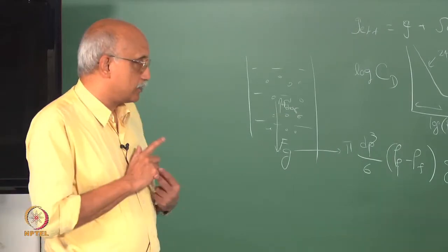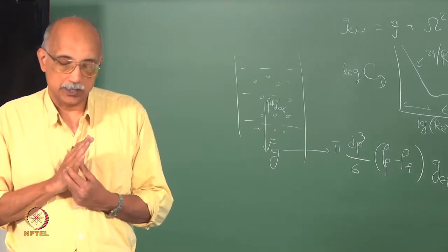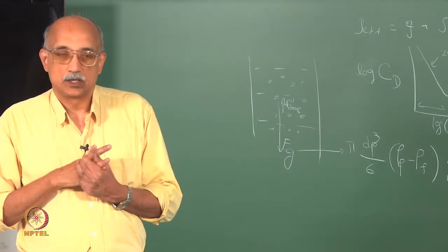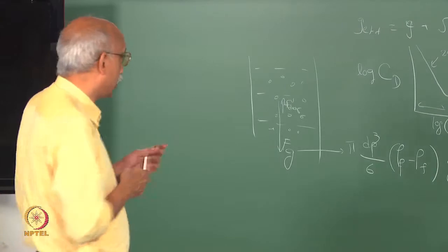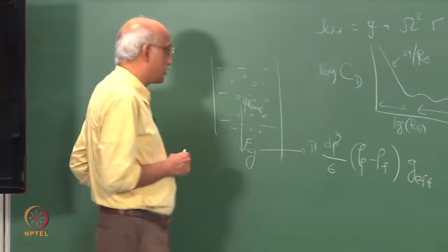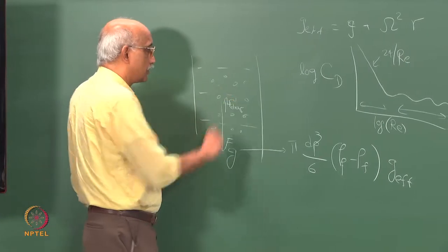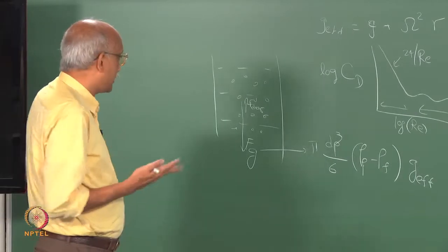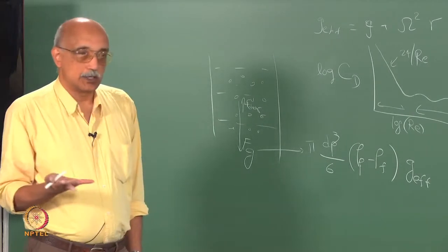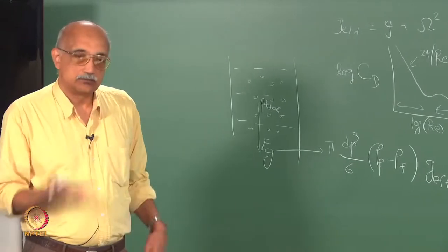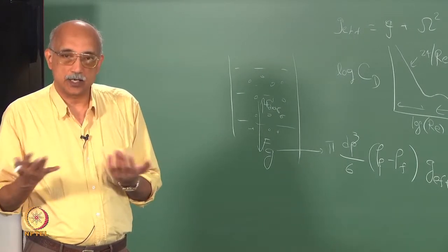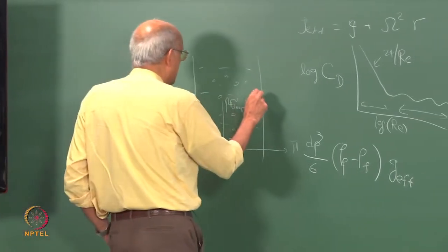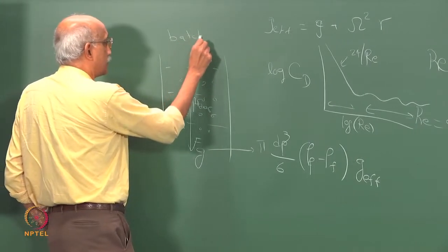But the reason that this is a very important mechanical operation is that it is a very effective way to separate particles by size and mass. So, if you have a column, this could be a sedimentation column, and you are trying to do size analysis, or trying to separate the material by size, a convenient way to do this would be to suspend the particles in a liquid and let them settle. They will have varying settling rates based on their size characteristics, and therefore you can separate them. This is called batch settling or batch sedimentation.